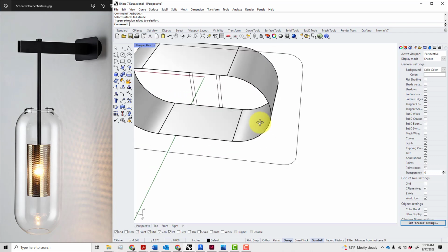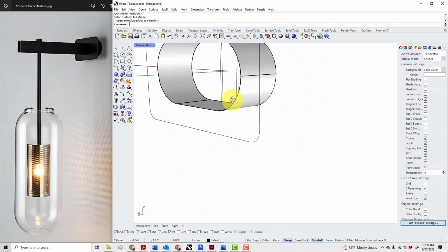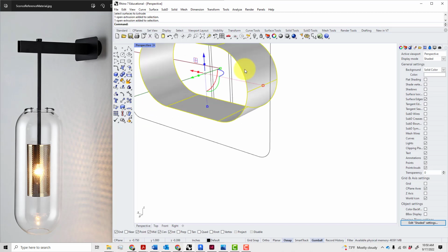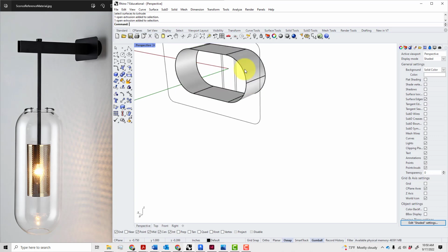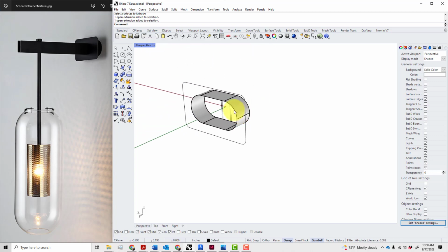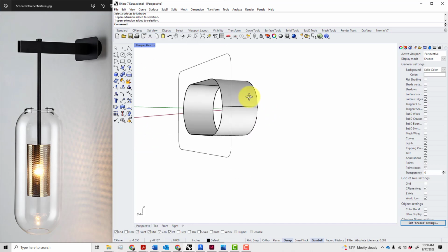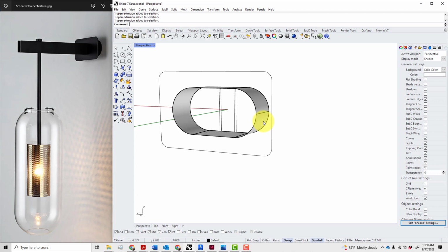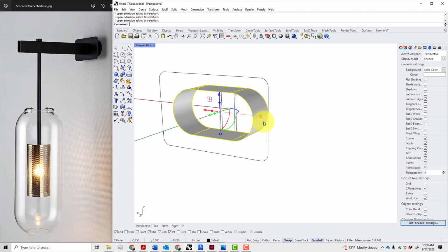What that means is that the surface obviously doesn't even have thickness, right? Because I haven't given it any thickness. I've just kind of rendered the surface. In some modeling software, that really doesn't even exist in the world until it has thickness. So I can give it thickness by, in this case, I can offset surface, and I want to flip.